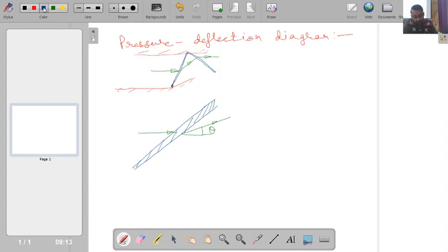Now if you consider the other shock wave, the reflected shock wave, its orientation is something like this. Here the streamline looks something like this. Say it is coming at a certain angle; it can come straight also. If I take these two as separate identities, a streamline coming like this will deflect something like this, and here I will have this angle as theta.